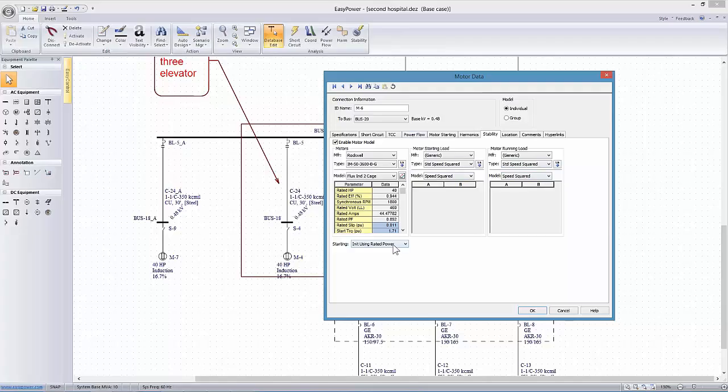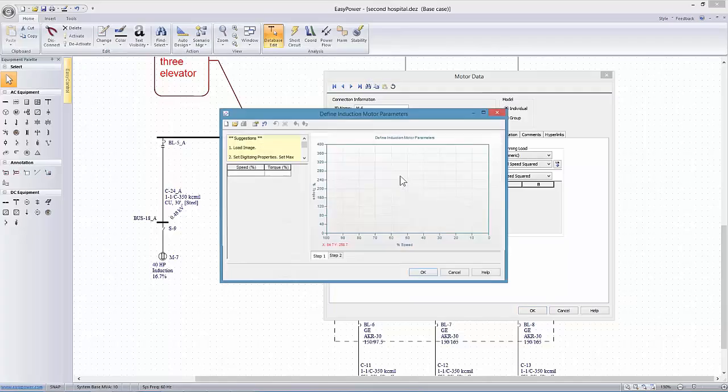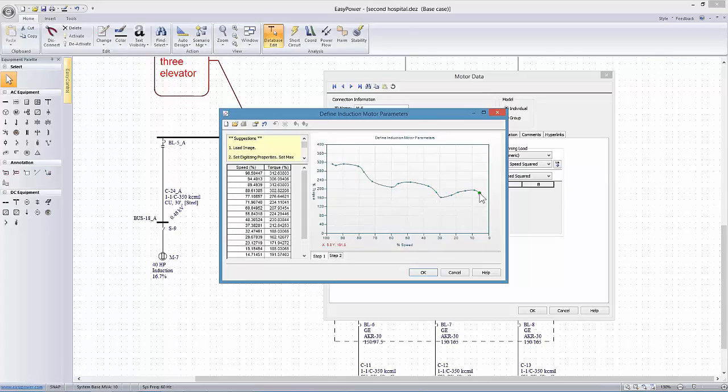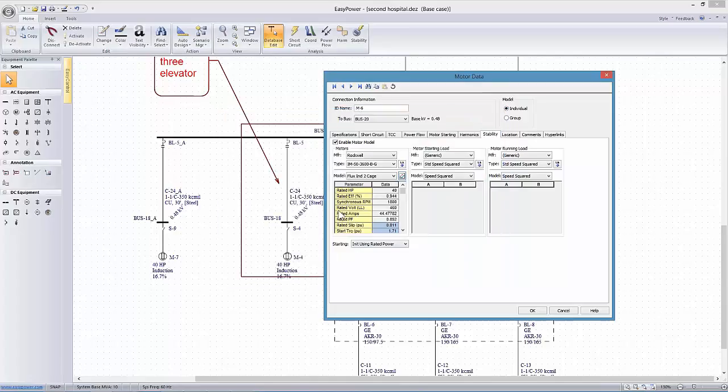And once these are all populated, then that's what the system used for the simulation. Now I mentioned if we don't have something close in the library, and we do have the torque speed curve, the tool allows us to actually go in and digitize based upon matching this drawing tool with the curve that we've pulled in a PDF format, and then it will translate this data into parameters that will correspond to what's needed by the model.